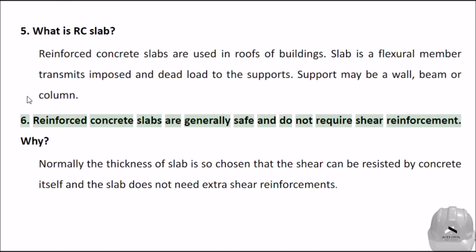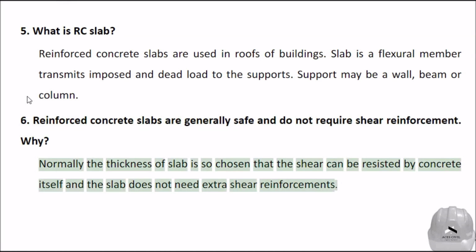6. Reinforced concrete slabs are generally safe and do not require shear reinforcement. Why? Normally the thickness of slab is so chosen that the shear can be resisted by concrete itself and the slab does not need extra shear reinforcement.